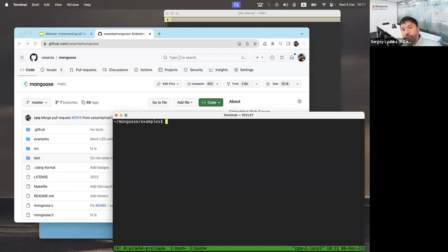Build all the networking functionality on the workstation, so to say, create your device emulator. Mock all your hardware calls and build on the workstation. Once you've built, debugged and tested it, maybe even hooked it up to a CI continuous testing environment, you can then move the networking functionality onto the embedded device.